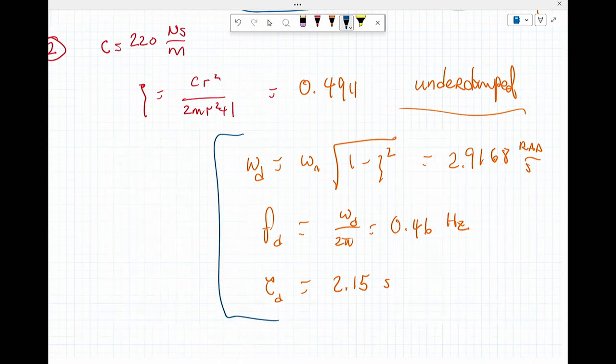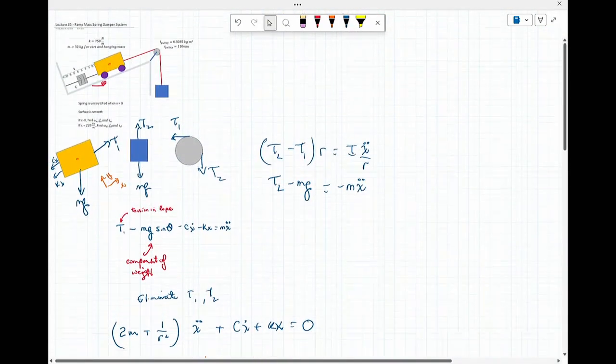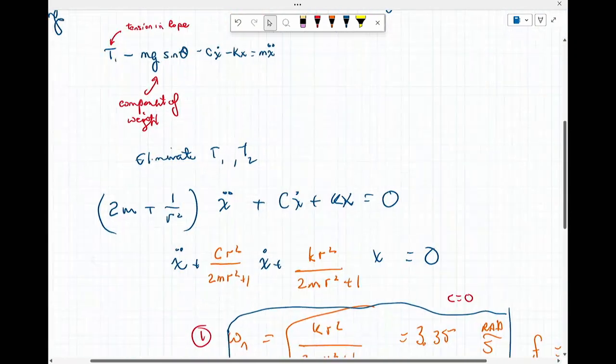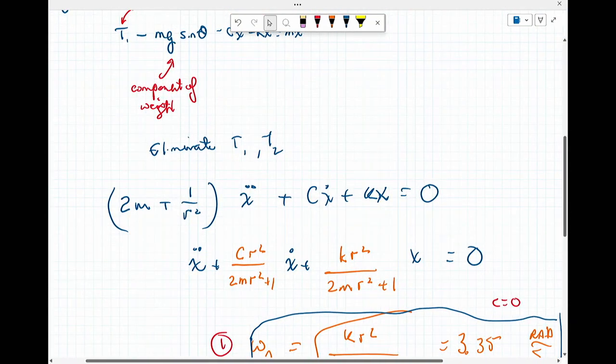It's not much harder to do these. Once you have the recipe book, once you apply everything, it kind of works out. But the interesting thing about this particular problem is that, yes, it is a mass spring damper system, but the omega n of the system is not the square root of k over m. You have to solve through, and this is why in all of these problems you are writing out the free body diagram, getting to this form of the equation, and then solving through.